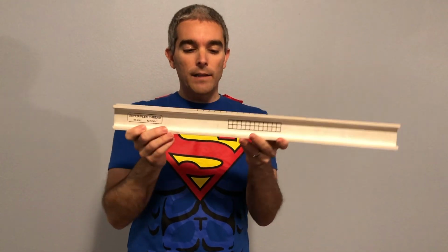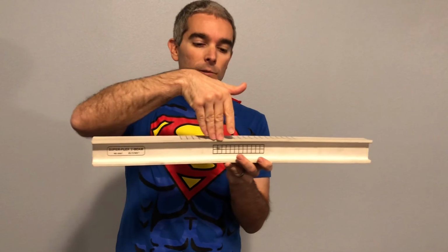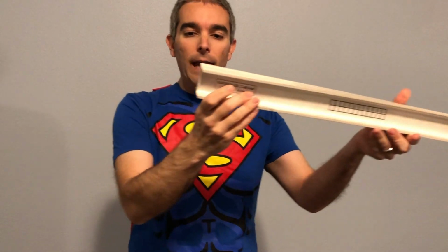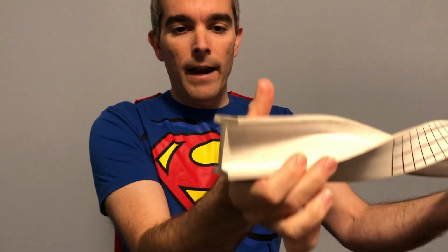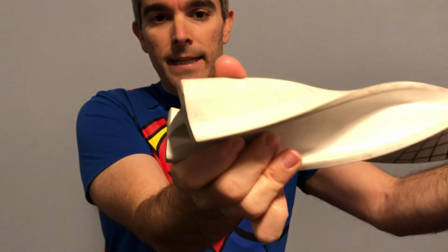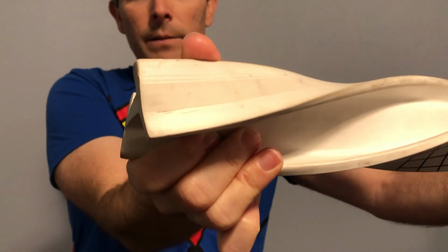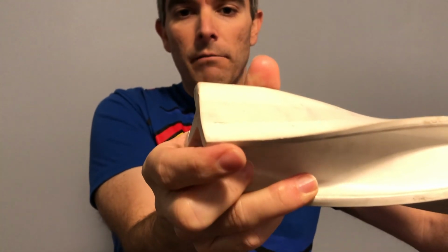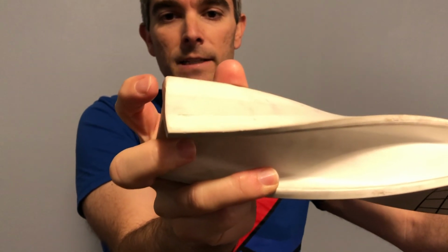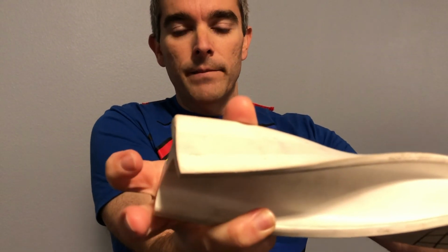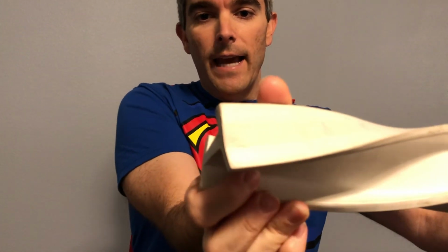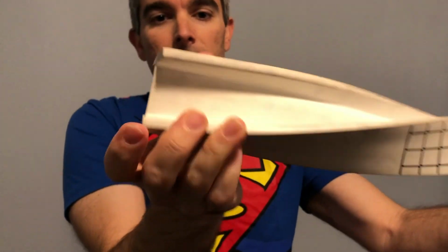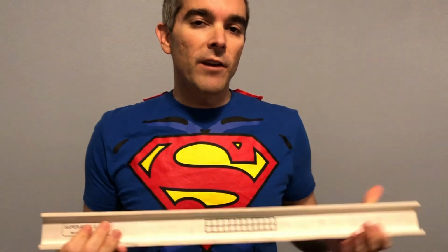So what does that look like? Say, for instance, we didn't have a load that was through the center of gravity, and it ended up creating a torque on our I-beam. For the I-beam, you can see that as it torques, and I'll exaggerate it here, the cross-section at the end is not in one plane anymore. You can see that the top flange here has moved to the right, and this portion of the flange has moved to the left, and then at the bottom, the flange is opposite. You can just see how it's kind of racked there, and it's no longer one plane in the cross-section at the end. So that's the problem that shear stresses can lead to.